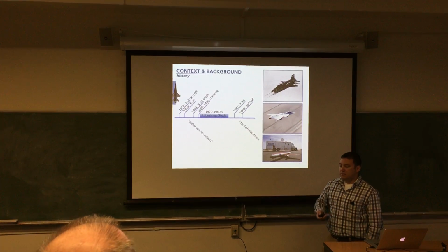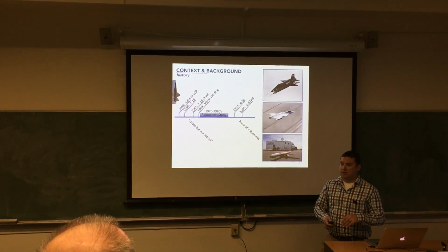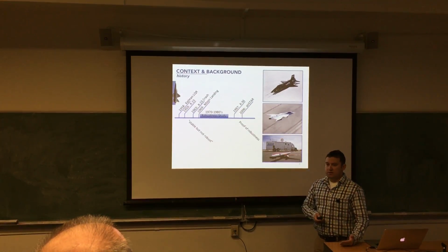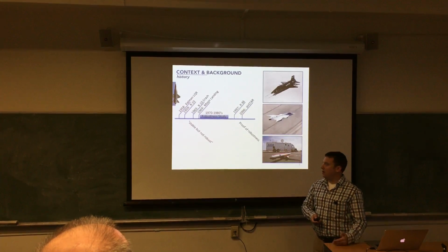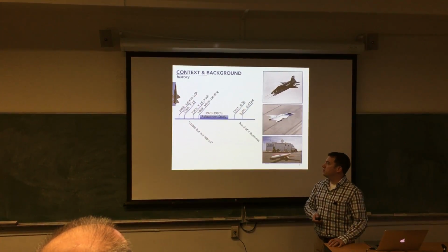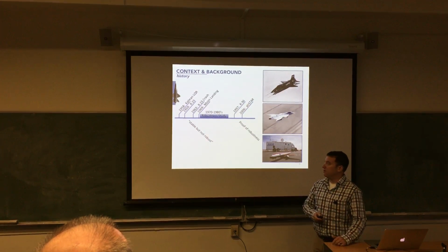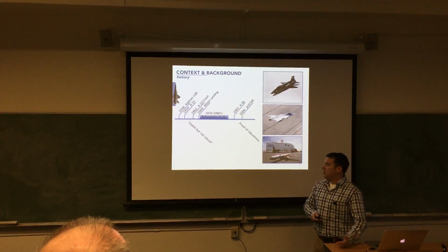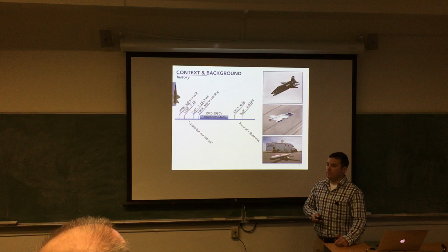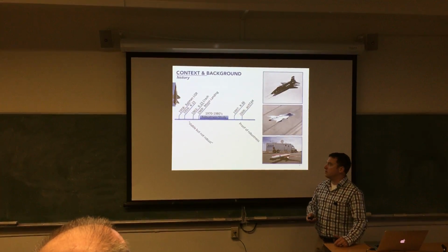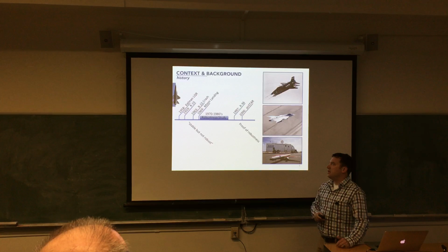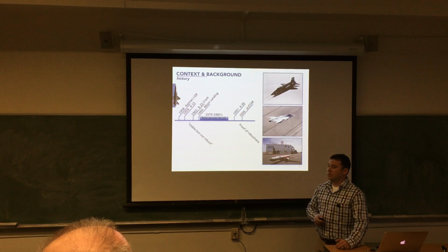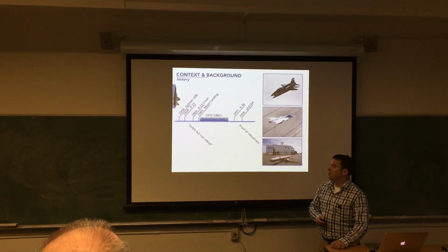However, towards the later stage of the development, because of the high dynamic pressure of the aircraft, the dynamic range of the aircraft, they wanted to move towards an adaptive control strategy to help mitigate some of those issues with the aircraft being non-time variant. What ultimately ended up happening was their understanding was very nascent and naive for robustness characteristics of these kinds of controllers. And so ultimately in 1963, the adaptive controller resulted in a complete departure of controlled flight, ultimately killing the pilot at about 63,000 feet.